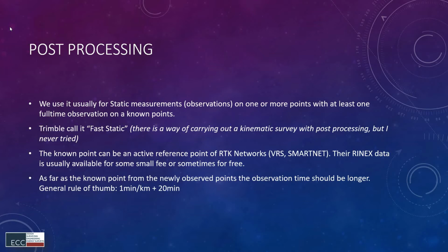So it's a little bit different. When I did it for myself, it was a fast static base and a fast static rover, 2 settings. And then when I go during the day with the rover, I'm just choosing that one, the fast static rover. And then at the end of the day, I go back and connect again to the receiver.